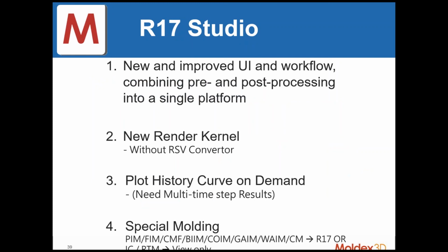Yeah, so just a quick summary. Studio is a new and improved user interface and workflow, combining both the pre-processing and the post-processing into one single platform. That render kernel, getting rid of the converter, having things like the probes and the plot history curves on demand. And then R17 is going to also support these additional specialty molding applications, in addition to the conventional injection molding that's currently available on R16.